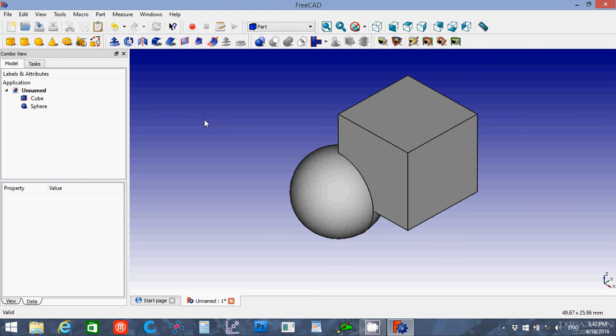The reason you don't use Control Z to undo is it is very unpredictable. If you click Control and Z, it may make the entire part you were working on disappear entirely out of the project, rather than just taking you that step back.